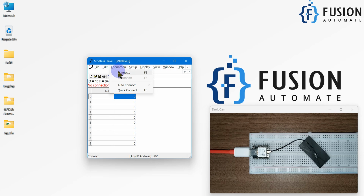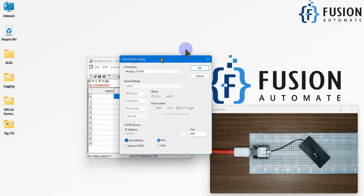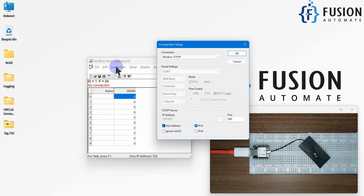Now I can go to Connection, click on Connect, and select Modbus TCP/IP communication, because this ESP32C3 board is capable of Wi-Fi communication. Here is the Wi-Fi antenna, so it will connect to my Wi-Fi and read the data from this Modbus Slave software wirelessly. The Modbus Slave software will act as a Modbus TCP device or Modbus TCP server, and this ESP32C3 board will act as a Modbus TCP client. It will read the data of my Modbus TCP device wirelessly.